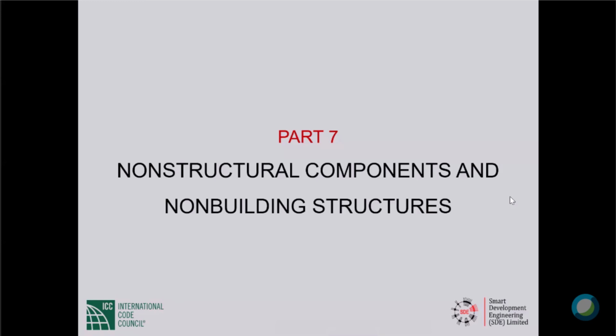Which load case or combination shall be considered for checking torsional irregularity? Torsional irregularity does not have anything to do with load combination, is it? Torsional irregularity, as I gave you, is when you calculate the deflections. Again, I see. Okay. My answer will be the same. We are talking about the lateral deflections. And when we are talking about torsional irregularity, we are really talking seismic. So it is the deflections under the strength level seismic forces that are important.